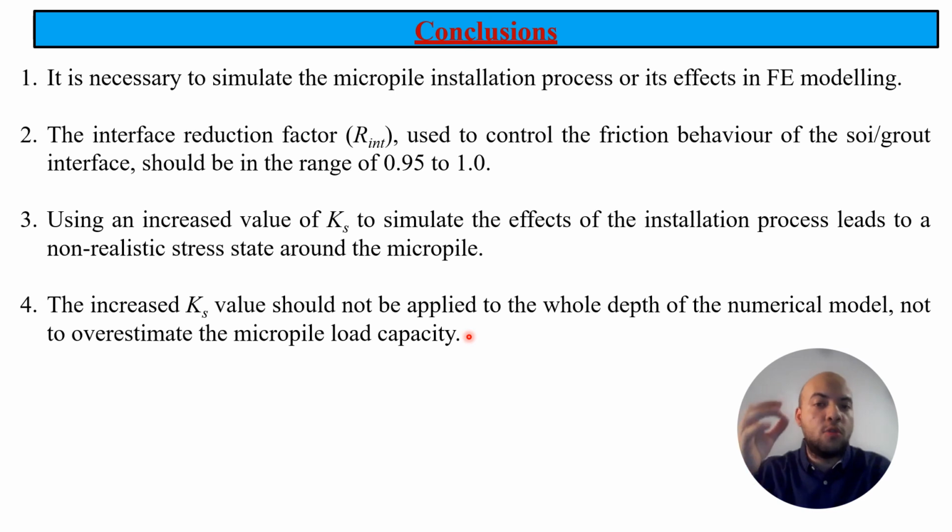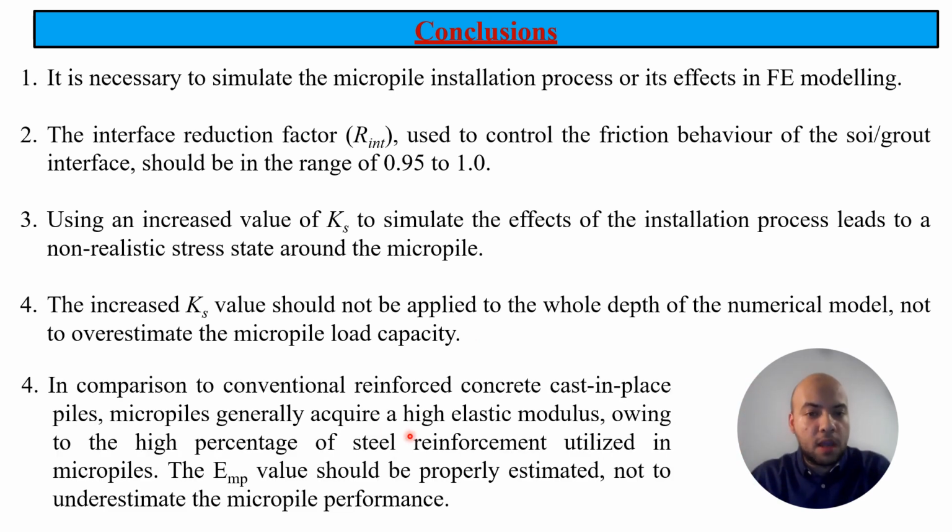You should apply it to a specific zone around the micropile, and in comparison to conventional reinforced concrete piles, you must correctly estimate the value of the elastic modulus in order to get the best and most accurate results in Plaxis.